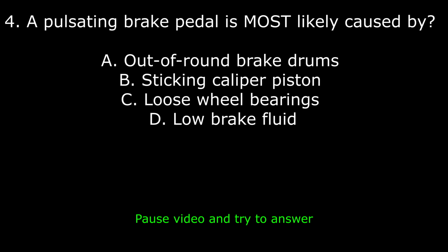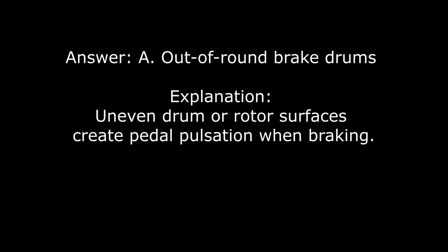4. A pulsating brake pedal is most likely caused by A. Out-of-round brake drums. B. Sticking caliper piston. C. Loose wheel bearings. D. Low brake fluid. Answer: A. Out-of-round brake drums. Explanation: uneven drum or rotor surfaces create pedal pulsation when braking.